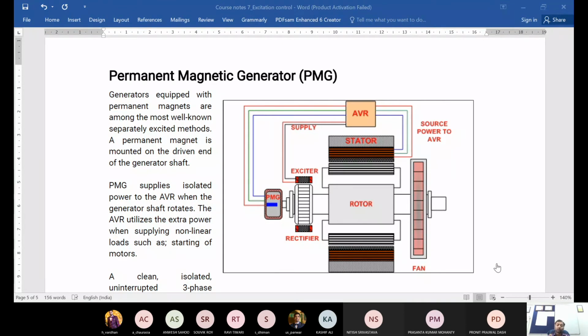But nowadays we have a lot of electronic gadgets, known as the IT load, information technology load: computers, laptops, and even the CFLs and tube lights. All of these have a much more complex relationship between voltage and current, something different from simple Ohm's law. Ultimately, if you resolve that, you see it has a bearing on the power factor as well, and a much more stringent requirement in terms of reactive power demand. That's why reactive power demand has become very substantial these days, and a very crucial component of the supply.